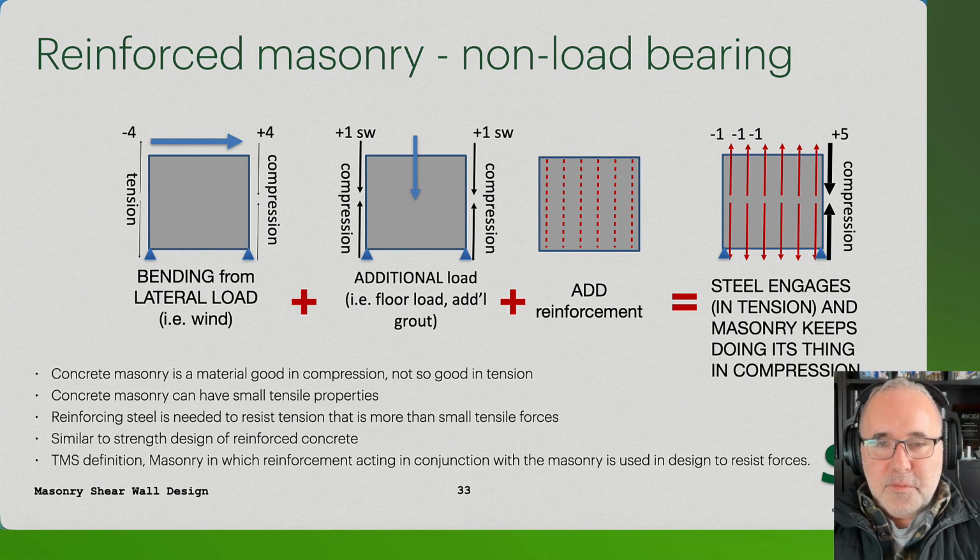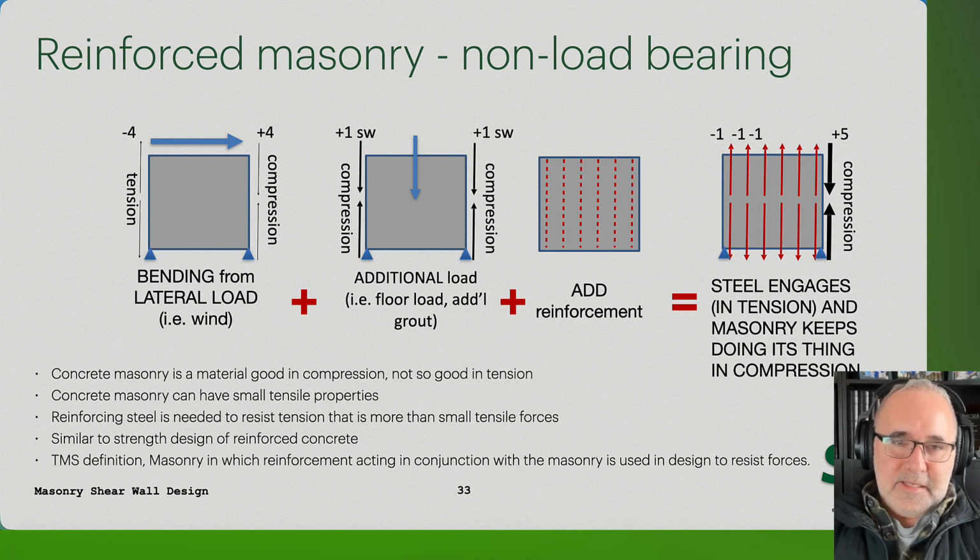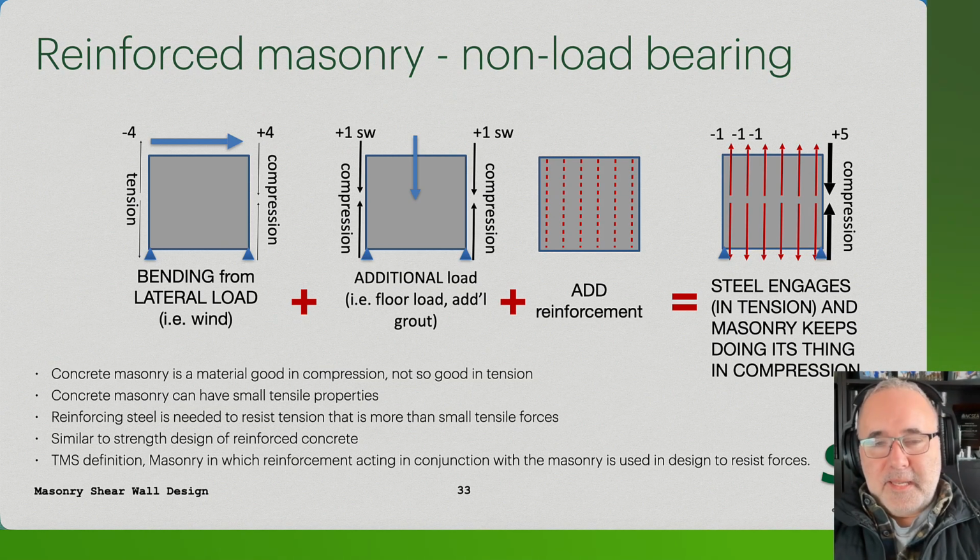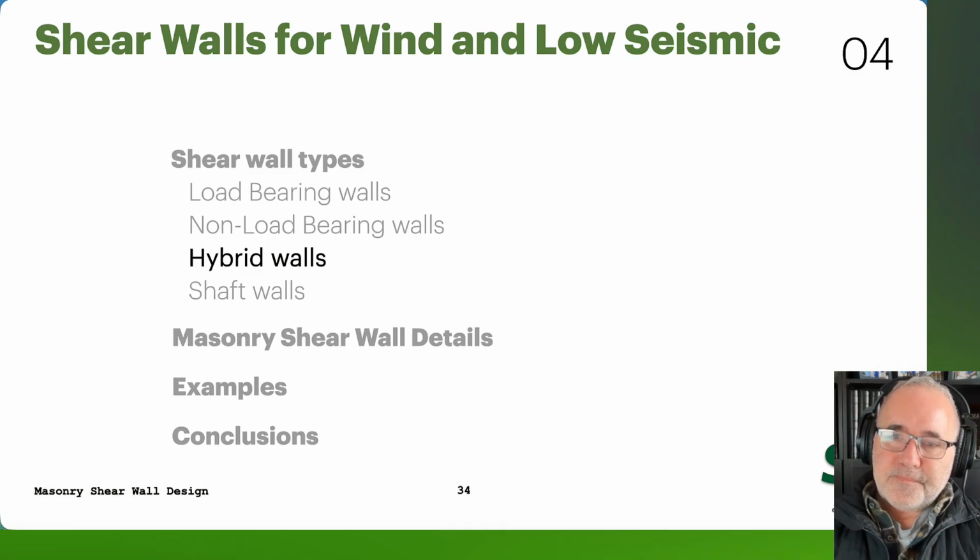And for those non-load-bearing elements, you have a lot more tensile forces. We just have the self-weight and the shear forces. So what we're going to have is more tensile forces accumulating in the masonry shear wall, so maybe more of a demand for reinforcement than if you have some load on the wall. Non-load-bearing walls certainly can be shear walls, can be pretty effective as shear walls, but there's likely going to be more reinforcement needed in those types of designs.